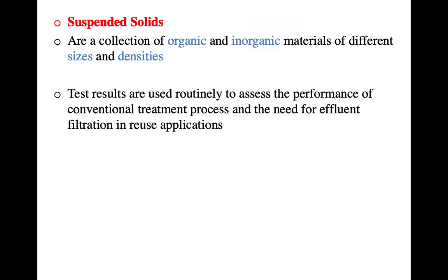So there are solids, minor solids. The minor solids can also be found in water, and these are a collection of organic and inorganic materials of different sizes and particles that could be present in a given water body. Here, we normally conduct routine tests, and these routine tests give an indication of the performance of conventional treatment processes and the need for water, especially effluent, to be filtered if it is supposed to be reused.